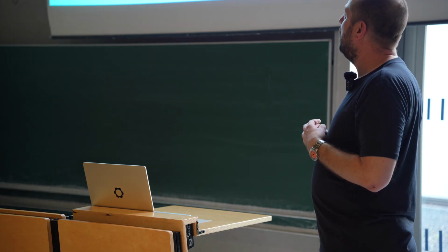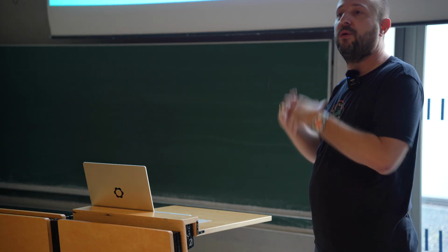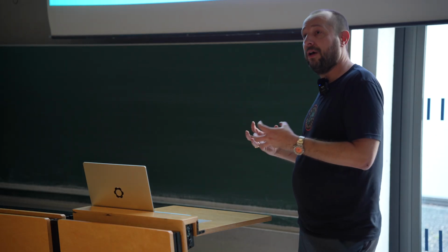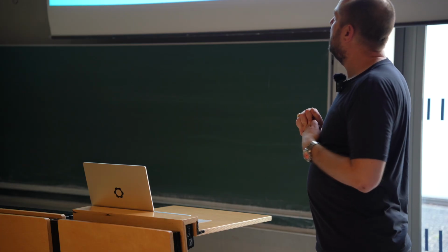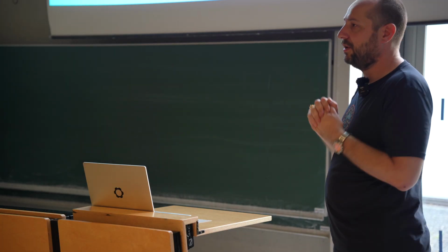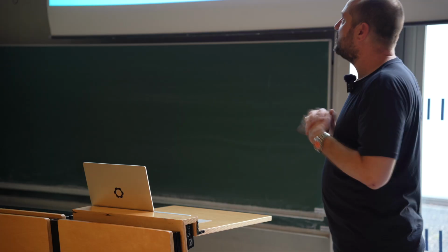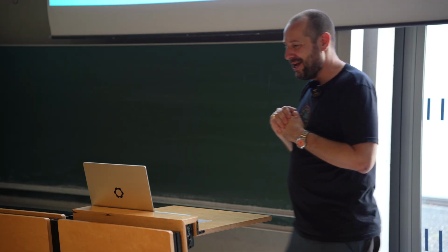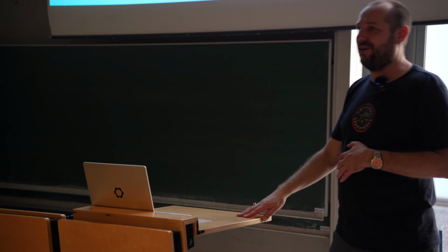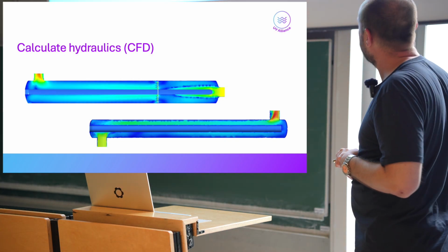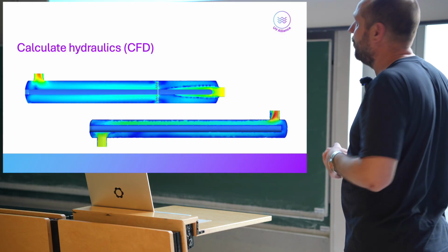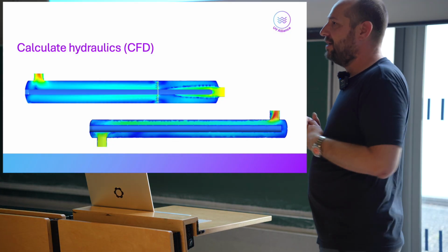There are appliers, developers of UV systems that only do that. They calculate a light field, they assume a plug flow, and they say this is the average UVC and this is the average dose, and that's good enough. This is not the best solution because water doesn't flow like a plug flow always, or generally not. So how the water flows along that lamp is really important. The top example is a system from us. The bottom example is a more old school, easy system.